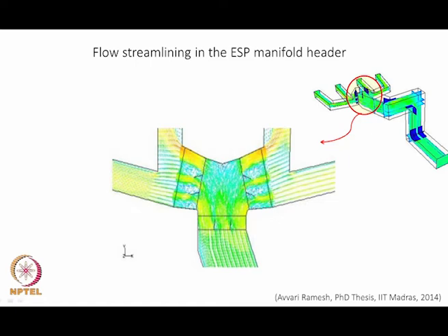So you can put guide plates here, you can put some guide plates to correct the imbalance between this flow and this flow, and then you can put some guide plates to persuade the flow to go into this and into this. On what basis do we put the guide plates? To do this experimentally would mean that we have to build this whole thing in our lab and then try various things, and it will take months and it will be very expensive.